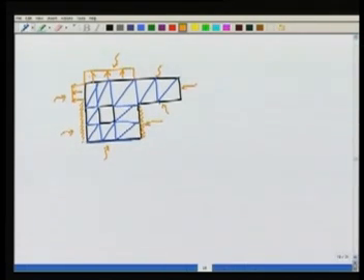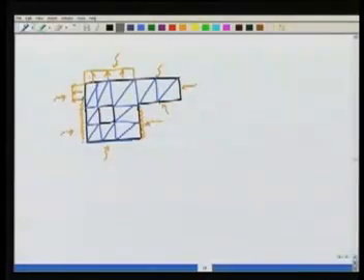So actually a global geometric edge may have subsections where boundary conditions are changing, and we have to honor this transition or change of boundary conditions by putting nodes at those points where the boundary condition transitions. So this mesh is actually unacceptable, because here is a point where the boundary condition transitions, and I have not put a node there. So in a very simplistic way, I should have a line like this. I am just simply dividing the mesh, and if I have this line, then I will have to now mesh it like this.